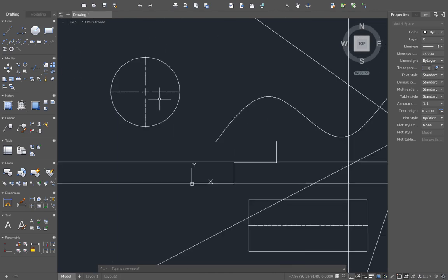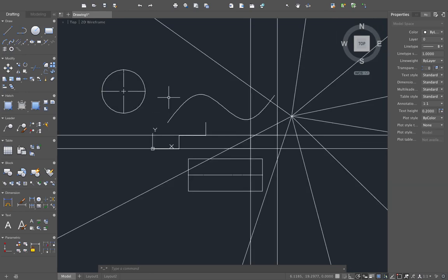It is also required when we draw complex objects, or when we need to give dimensions or show the center point of the circle or any arc. To use this command, type CM enter and then click the circle, and it will make a center mark.